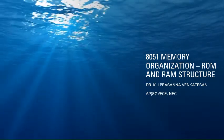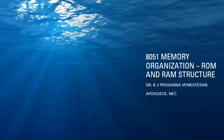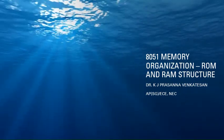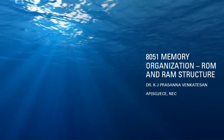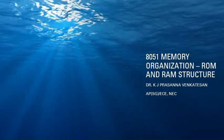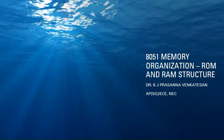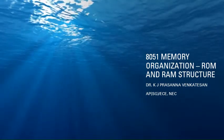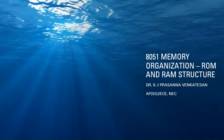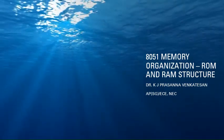As we saw in our previous video on the difference between microprocessors and microcontrollers, a microprocessor is an IC which only has a CPU inside it. It does not have RAM, ROM or any other peripherals on the chip. A user or system designer has to externally install these peripherals to make the system functional. In contrast, a microcontroller is a device that consists of a fixed RAM, ROM and other peripherals like timer, interrupt, and ports embedded on a single chip.